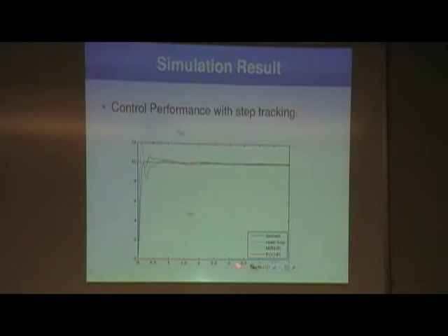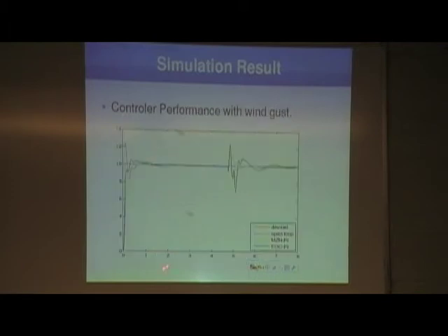We can see here that in the open loop there is a lot of overshoot. For comparison, we have a classical modified Ziegler-Nichols tuning rule, which can generate Kp, Ki, and Kd, and we can see that this modified Ziegler-Nichols is not as fast as the fractional order controller.